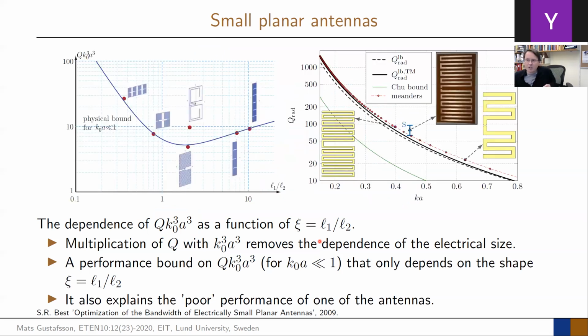And then you can ask the question, can you actually get a lot of antennas designed in these cases? Yes, you can. So the first cases here, you can see it was just normalized with the Ka. If we do the same and we keep the aspect ratios instead, so I say now I have an electrical size here between 0.2 up to, yeah, this is the half wavelength dipole, half of that one is a quarter of a wavelength at 0.8.